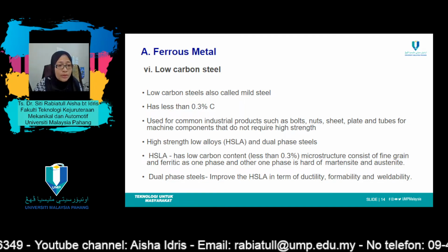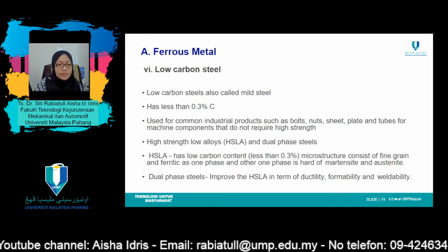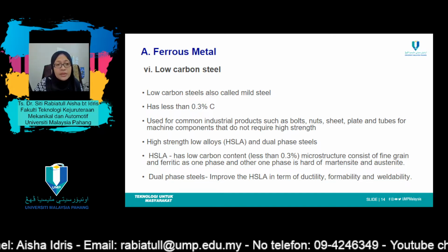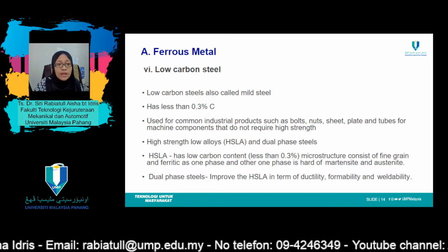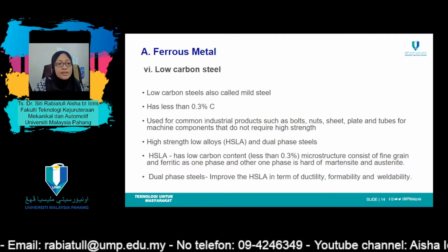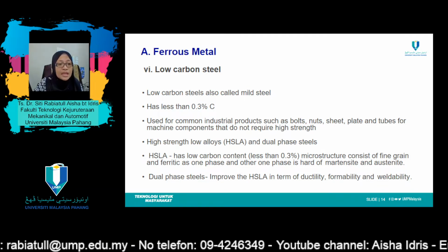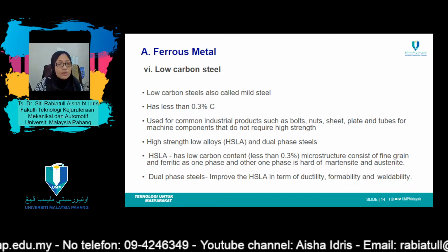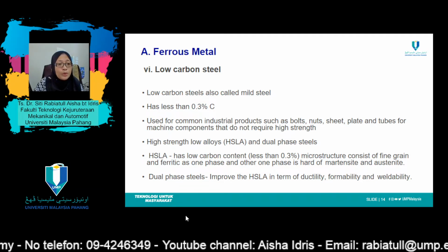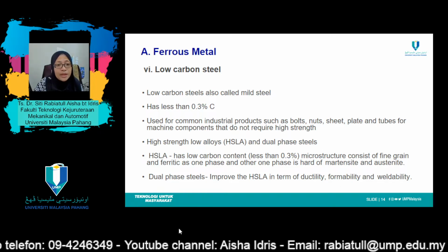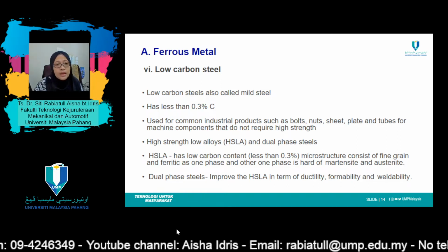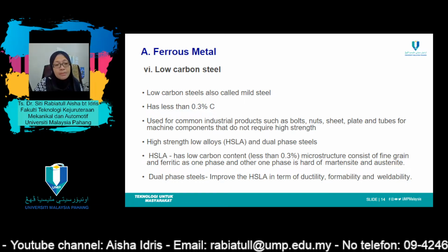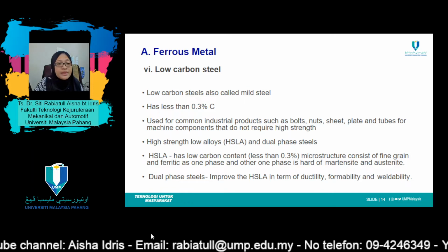As a consequence, these alloys are relatively soft and weak but have outstanding ductility and toughness. In addition, they are machinable, weldable, and of all steels, this type of carbon steel is the least expensive to produce. Examples of applications include automobile body components, structural shapes like I-beams, channel, angle iron, and sheets that are used in pipelines, buildings, bridges, and tin cans.